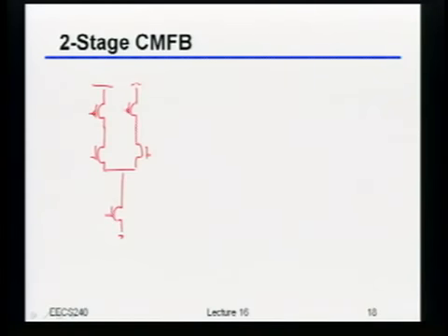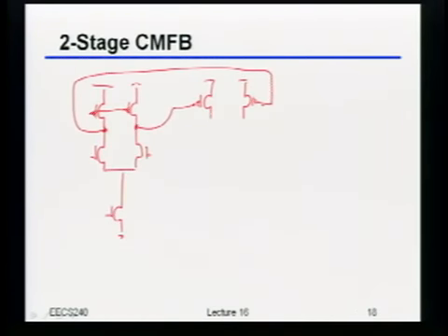And again, I want to do a multi-stage amplifier just to get some additional gain out of this thing. So let's say there's some bias right here. Since the biasing works out much better than some of the conceptual designs I showed before, typically you'd want to use a PMOS for the second stage over here. And let's say I really do tie it up the way I've shown right there, so the second stage is now going to be pseudo differential. Then I'm going to have some current sources to bias this thing right here.